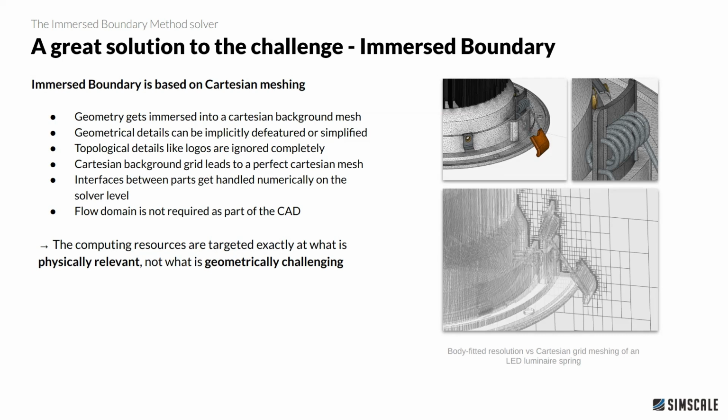So it's really helpful. Another benefit is for sure that as we have only Cartesian like hex cells, we have kind of a perfect mesh. Obviously, there is some transition between larger and smaller cells in the refinement regions, but we don't have really terrible skewed elements that screw up essentially our whole mesh, or you might know these type of elements if you have small gaps problems around these, etc.